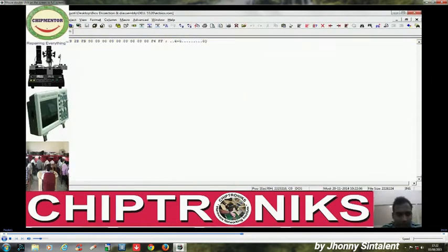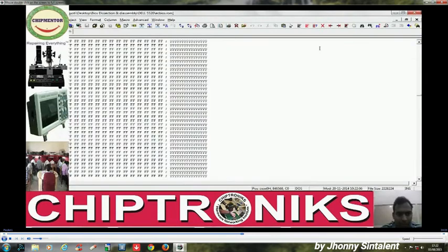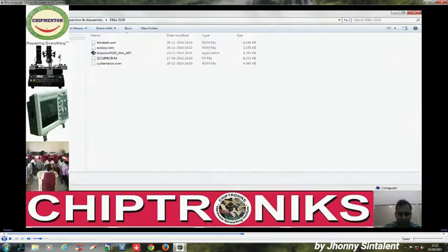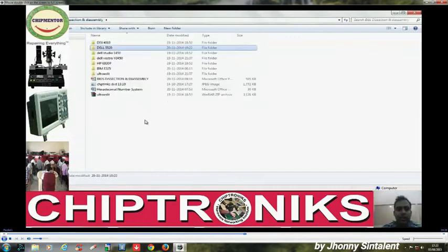So this is EC BIOS, and we got EC BIOS and system BIOS. Some programmers may sometimes give you an error, but not with this Dell 5520. I've never observed it with this, but if they give you some error, then you have to delete the file after 2048 KB. So this is the way we have got EC BIOS and system BIOS.